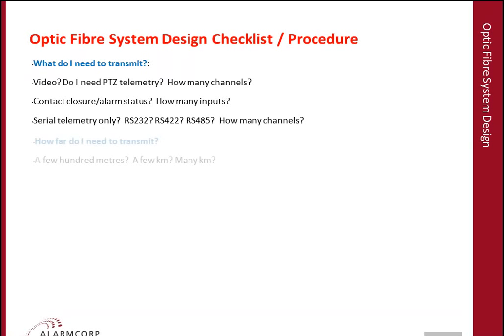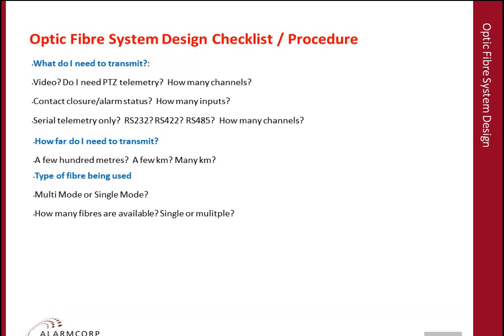So once we work out exactly what it is that we do need to transmit, we can then go on to the next step, which is how far do I need to transmit? A few hundred meters, a few kilometers, or many kilometers? And that will then pretty much tell us which types of optical fiber modems we need and also the type of fiber.